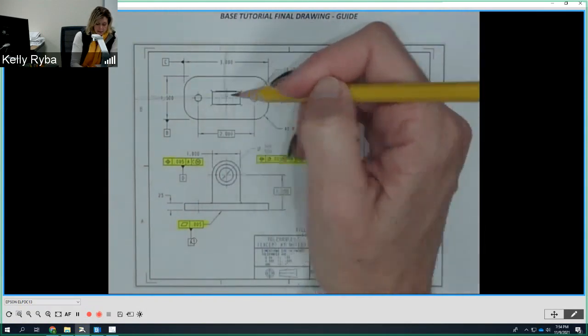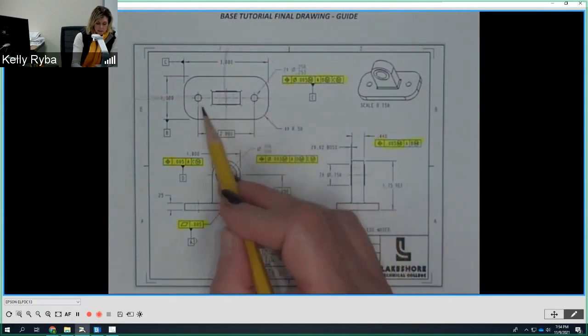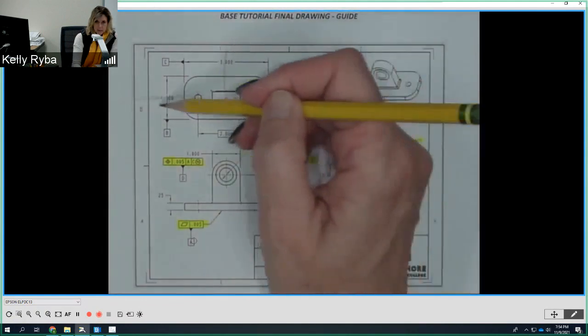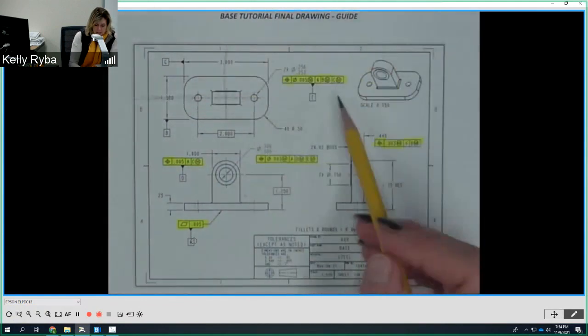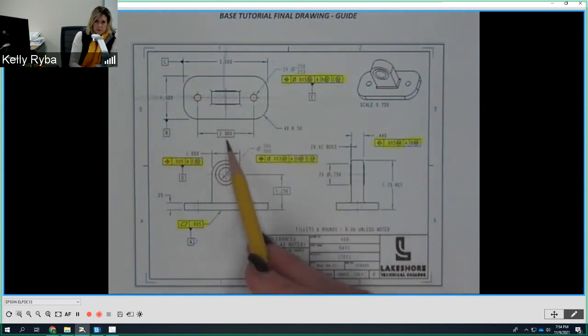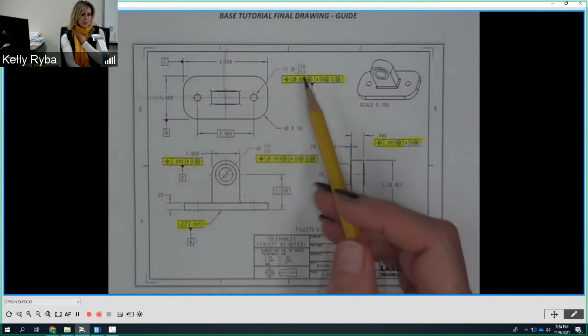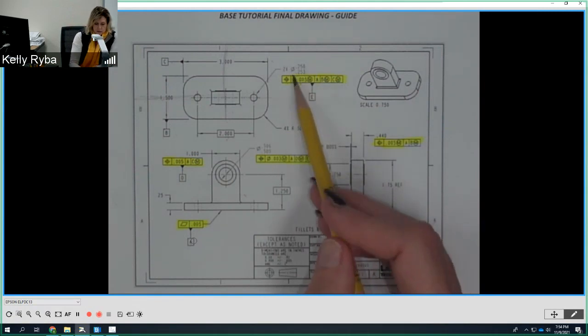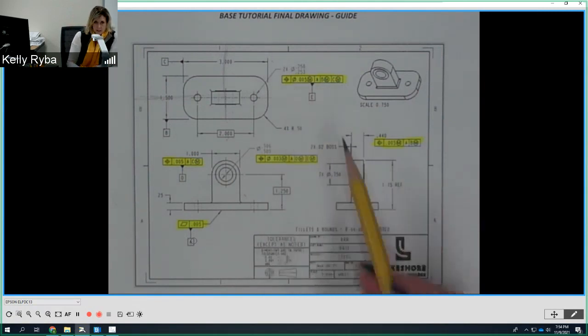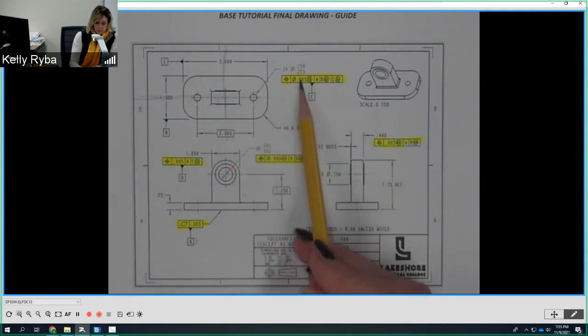And by doing that, then this 2-inch dimension is going to evenly space it on either side of the center plane here and then be in line with the center plane this way. Okay, so that's what we have going on here with those datums. We need to have the 2-inch being a basic dimension because it is going to be the relative location between those two holes, and we want to default our tolerance for that position to the feature control frame, not to the title block. And that's why there's a box around it. It says, don't look to the title block, look to the feature control frame for those two parts.